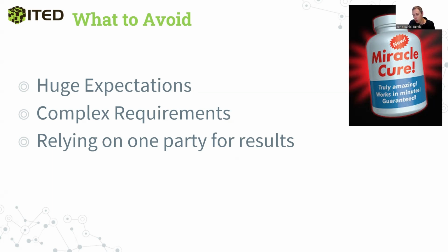Also, I mentioned that overcomplicating things, if you are new to BIM, is not a good way to start. If it's your first project, start with the basics. Ask for models, use them for walkthroughs, like I showed you how to do today, and have someone more experienced maybe help you with some specific tools to perform clash detection. You should always ask, if possible, to extract drawings from models and extract quantities. That gives a huge value, and I'll show you an example a bit later.